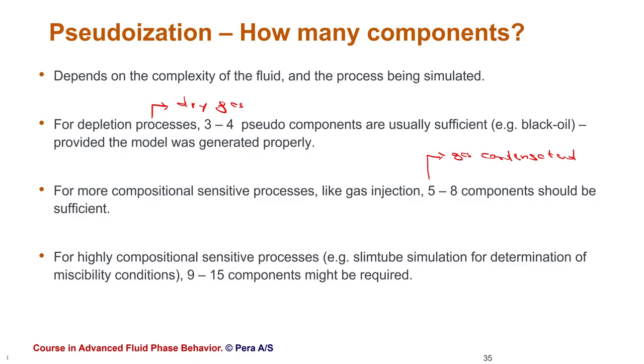you can use the cycling process to inject this. You can produce the wet gas, remove the condensate, and inject the dry gas back to your reservoir. This is called the cycling or recycling process. This kind of recovery method can be represented with 5 or 6 components accurately. However, if you are working with an oil reservoir, injecting gas, CO2 or a CO2-rich mixture of gas to generate a miscible flooding in your reservoir, you should include more components in your representation.